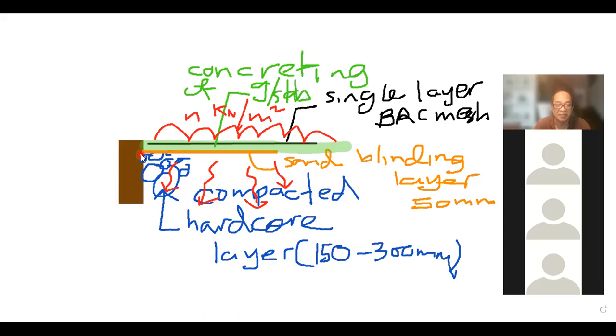It is a very economical solution in the sense that loading from the slab is not transferred to the ground beams, because if we transfer the loads to the ground beams, then the ground beams will carry the loads to the foundation, and the foundation will have to support loadings from the ground slab. But in non-suspended cases, we have our loadings supported directly by the soil below. Tanah yang support the ground. But the problem is settlement.